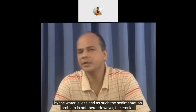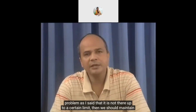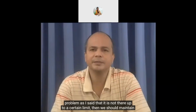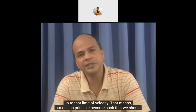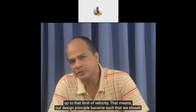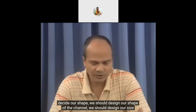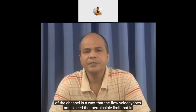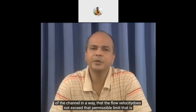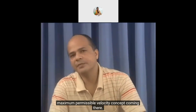However, the erosion problem is not there only up to a certain limit, so we should maintain velocity up to that limit. That means we should design the shape and size of the channel in a way that the flow velocity does not exceed the permissible limit. That is where the maximum permissible velocity concept comes in.